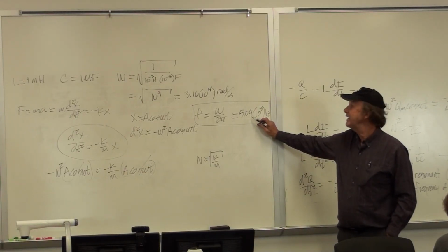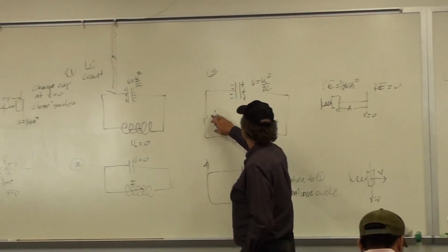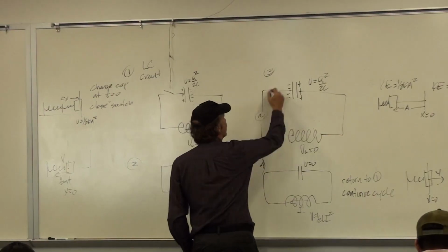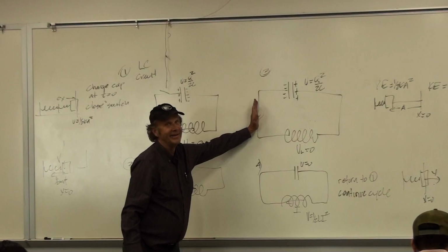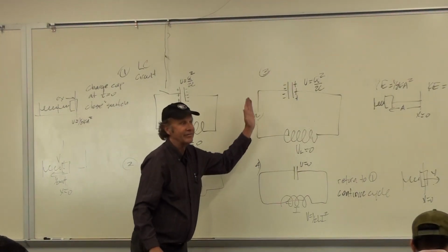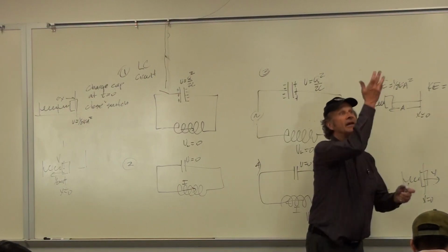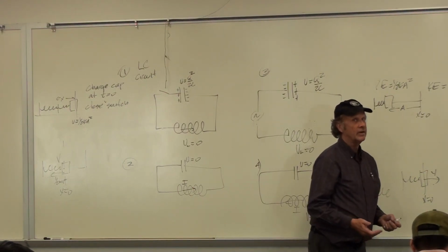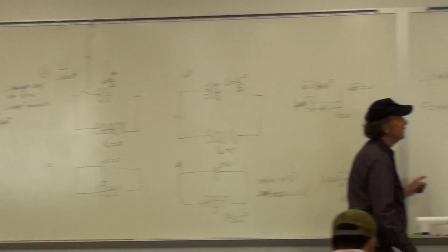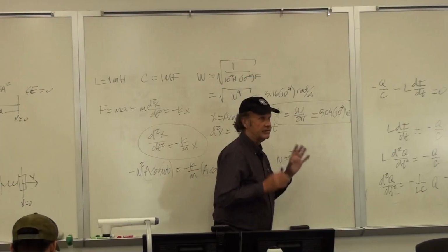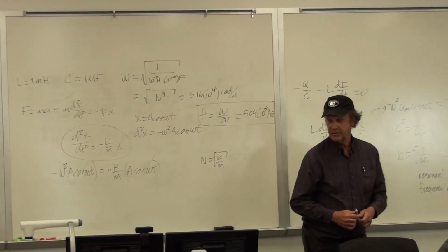Okay? So you find that natural frequency at which this system tends to resonate, and then you drive the system at that frequency with something that comes in from an antenna. So it naturally likes to vibrate at that frequency. Just like if you had a mass on a spring, you hit it at a certain rate, it vibrates a lot. If you hit it at the wrong rate, it doesn't vibrate very much. And so you can use this as what's called a bandpass filter to zoom in on one particular frequency that you want to observe.